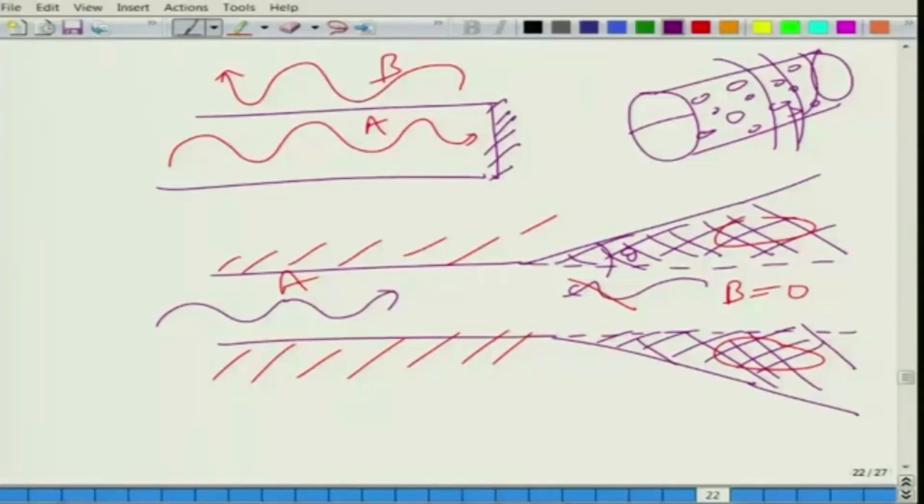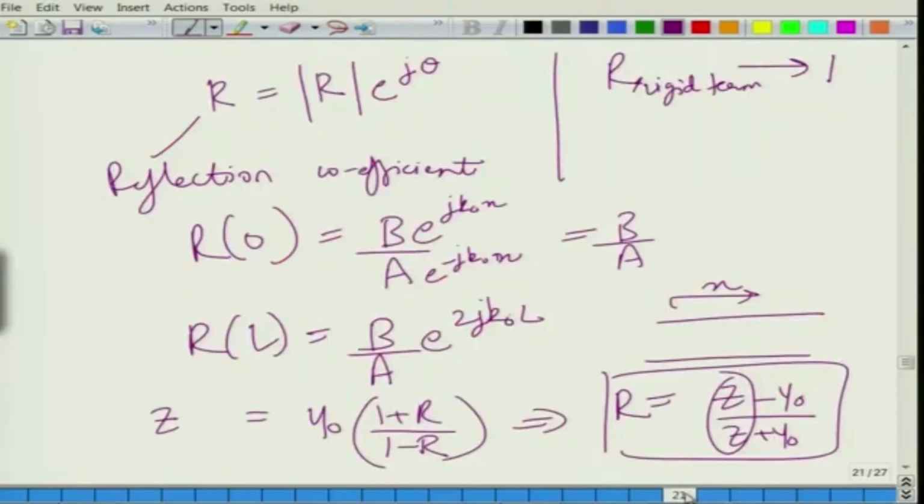The idea is that we can consider a termination anechoic beyond a certain frequency, much in the same manner as acoustic or anechoic chambers are designed. So, this termination is used in setting up a muffler testing rig, anechoic termination, using some parameters which we will cover later. So, the equivalent of a tube with anechoic termination equals the characteristic impedance of the tube.